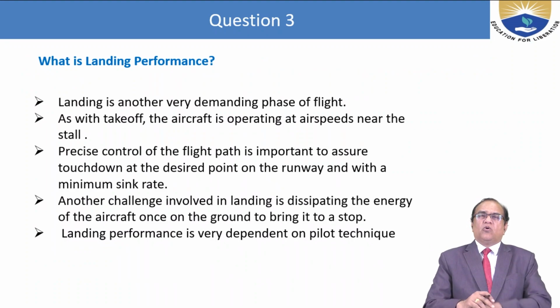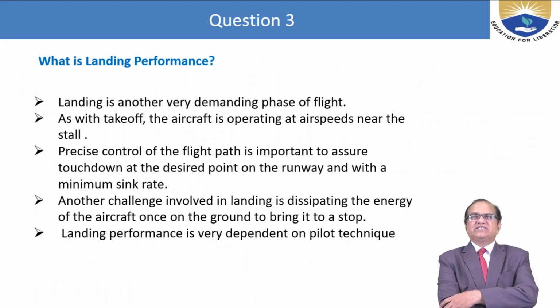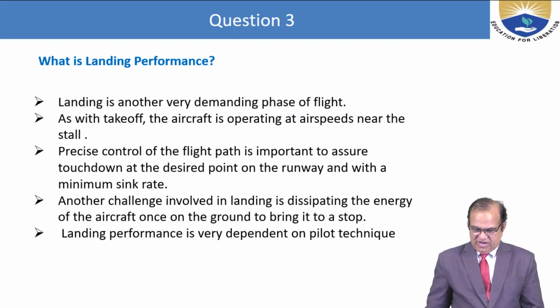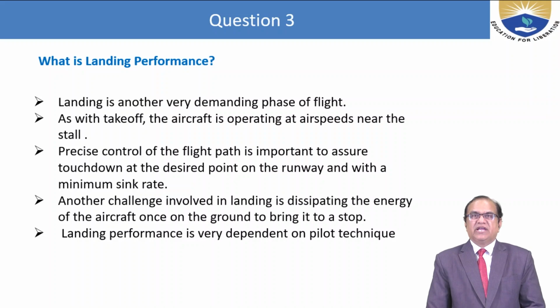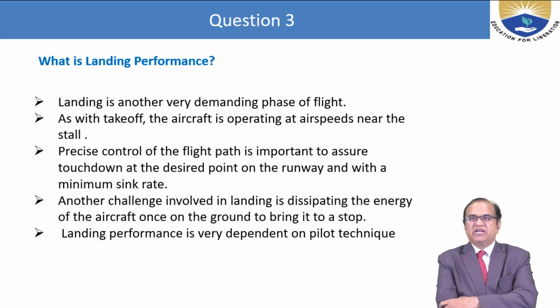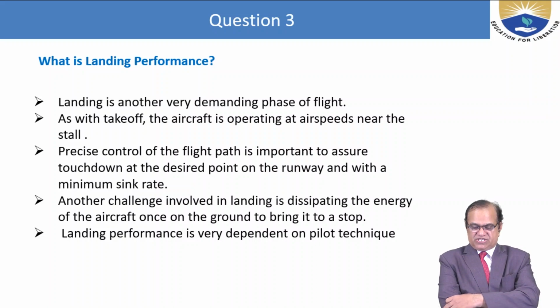What is the landing performance? Landing is another very demanding phase of the flight. As with takeoff, the landing is operating at airspeed near the stall. Precise control of the flight path is important to assure a touchdown at the desired point on the runway and with a minimum sink rate. Another challenge involved in landing is dissipating the energy of the aircraft once on the ground to bring it to a stop. Landing performance is very dependent on the pilot's technique.